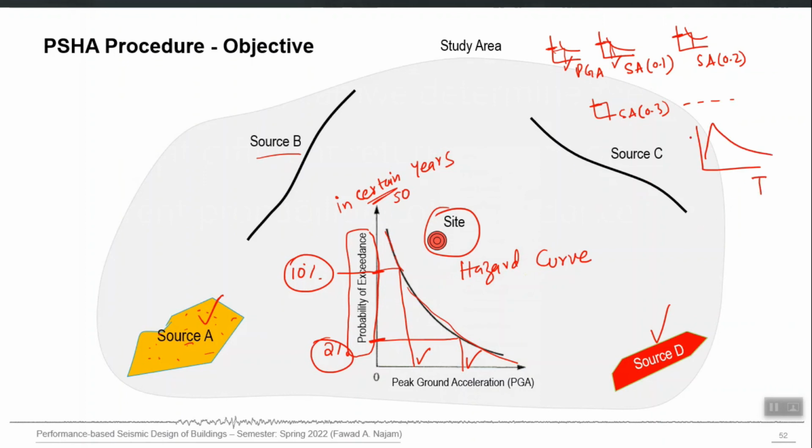Spectral acceleration versus time period. The starting point will be PGA, and then for any time period you know the spectral acceleration for one fixed definition of hazard. So if you use DBE level definition, 10% probability of exceedance, this is the curve for 10% PE in 50 years, or DBE level, right. So you can construct a DBE level curve from the PSHA for your site. Then you can also construct an MCE level curve, obviously that will be above this, or SLE level, which will be lower than even DBE level, or any intermediate level.